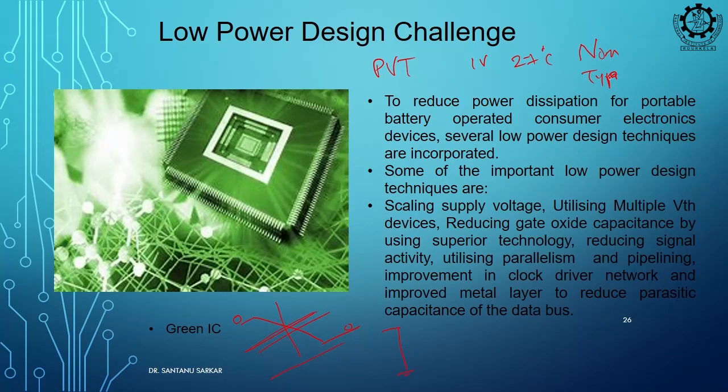When he is running, his voltage may degrade from 1 volt, you can consider 20% degradation, right. Temperature can change, room temperature can change, process can change. Process means there are generally 6 corners, roughly we say fast, slow and typical. Typical means exactly what you are designing, but if your mobility is getting higher, we will say fast process, your current will be more.